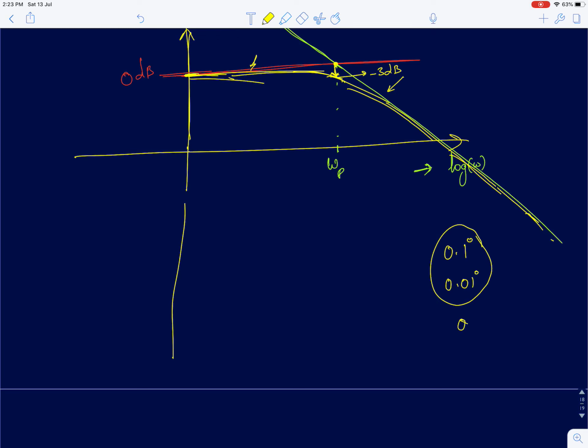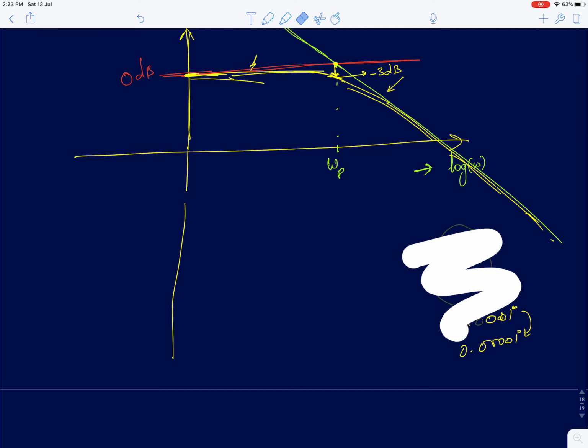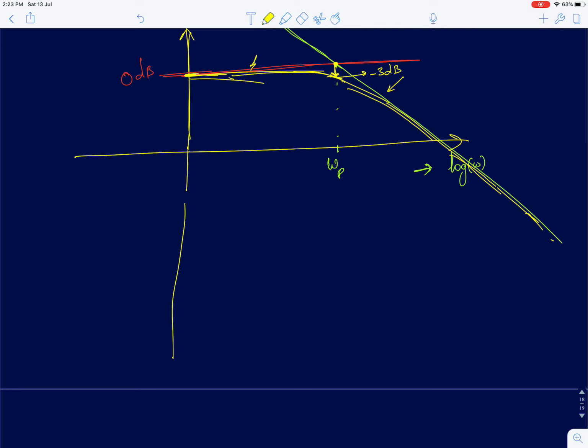Or if I go from 0.0001 degrees to 0.00001 degrees, it's 10 times less than this. It's really not going to look very different. But when the gain is different, it's going to look different. So that's why we apply logarithms only for the amplitude plots, and the phase response we still plot normally, only that the frequency axis is plotted on the logarithmic axis.